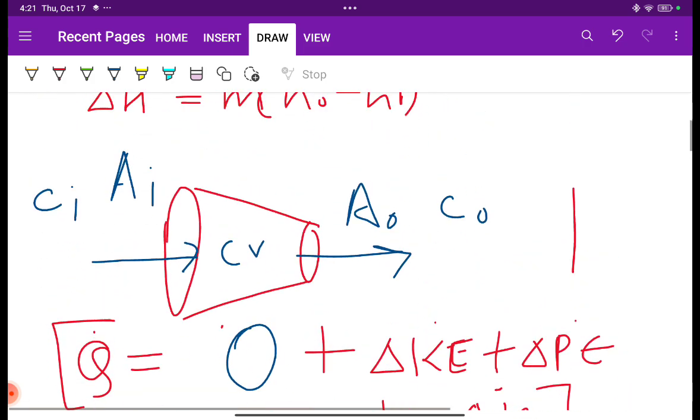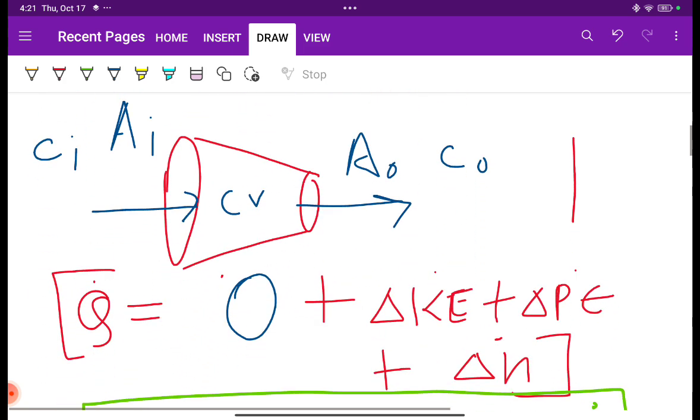And this is the case of the nozzle. The first case we studied was the nozzle. As I have said already, a nozzle is a steady flow device. It helps to increase the kinetic energy, and it is used in jet propulsion as well, and in the impulse turbine, at the inlet of the impulse turbine. And we see that the speed at output is quite higher than the speed at inlet.